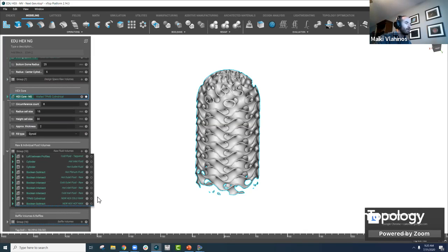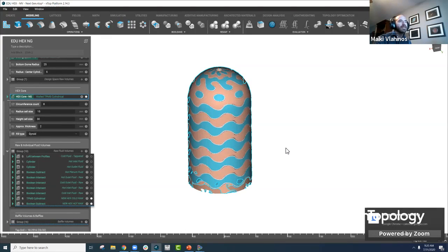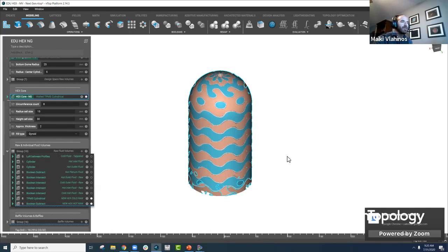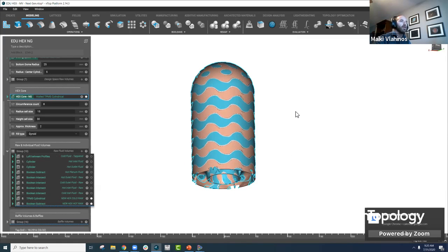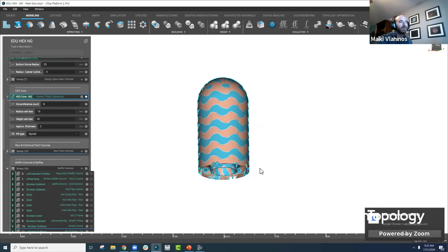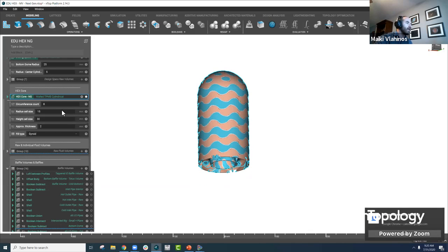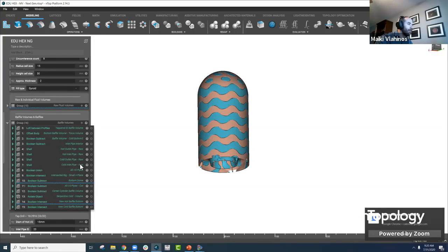And then from here, we simply create the fluid domains. That's one of the unique things about these structures: they inherently separate these regions of space. But then it's on us as engineers to figure out how to keep them from mixing. So all we need to do is intersect the fluid domains with whatever structure we want to be that baffle.